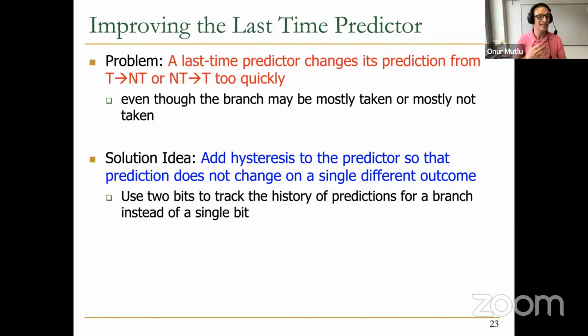Do you turn on the heater at that point? Right. Okay, let's assume that you turn on the heater right away, changing your mind quickly whenever the temperature drops or rises very little around 20 degrees. Then you basically keep oscillating, right? You keep switching on the heater and the cooler, heater and the cooler, and you never basically stop at a stable interval.